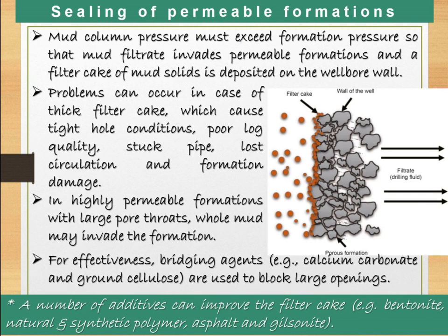It can even become very thick, which causes tight hole conditions, poor log quality, stuck pipe, lost circulation, and formation damage. In highly permeable formations with large pore throats, mud may invade the formation. Okay. For effectiveness, bridging agents like calcium carbonate and ground cellulose are used to block large openings.